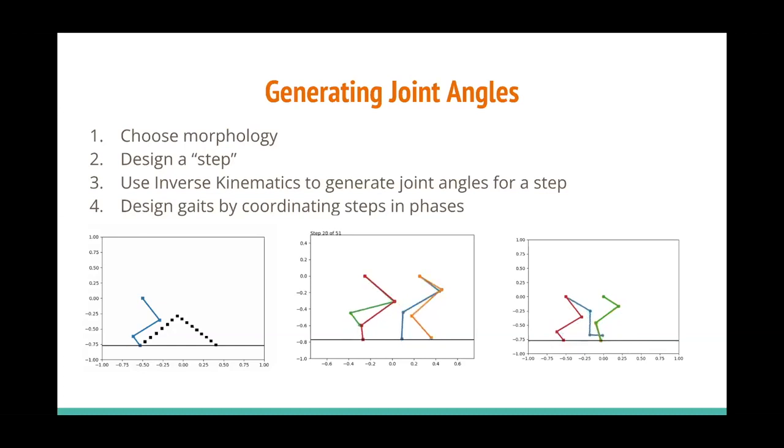Once that's done, the next highest joint will go. So that would be the knee in this case, and it'll also try to move as far as possible to point towards that first location. Once we've iterated through all the joints, then we evaluate whether we're at the location, in which case we move on to the next one, or if we're not at that location, we iterate through again. And this time, because the higher joints have moved, we have more mobility in the lower joints.